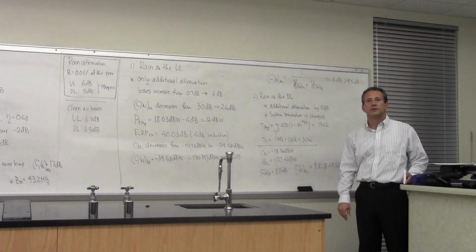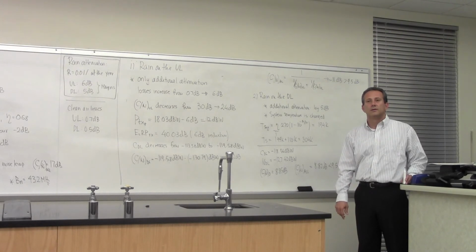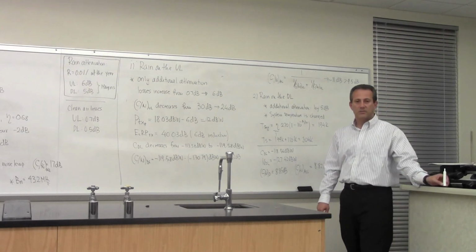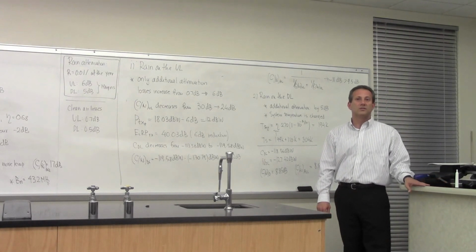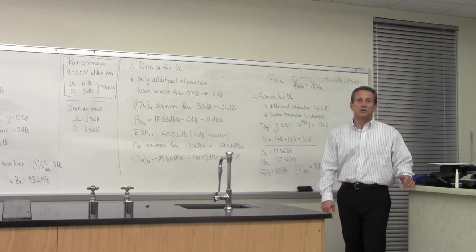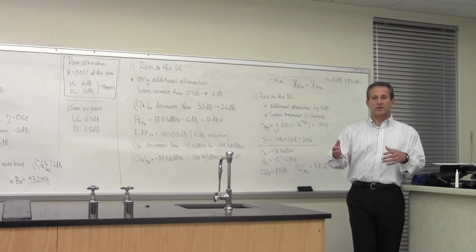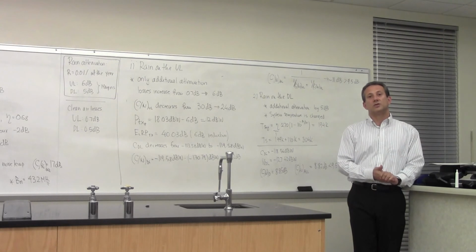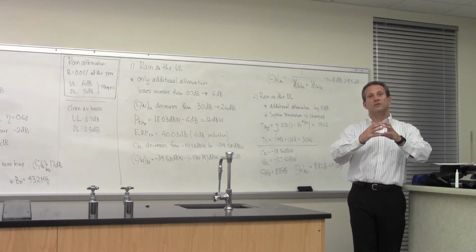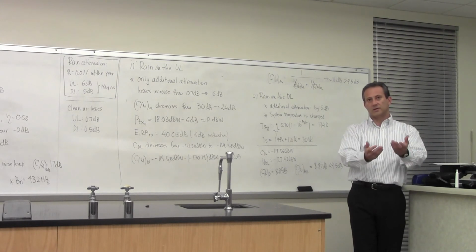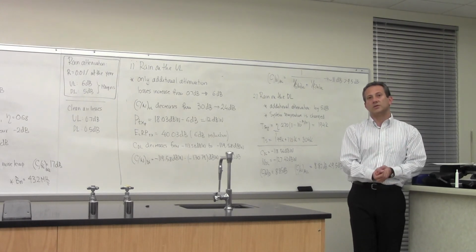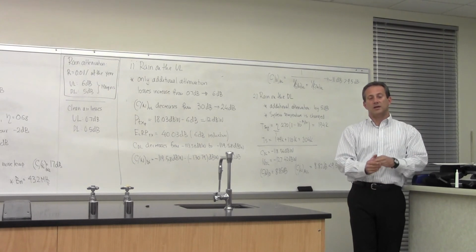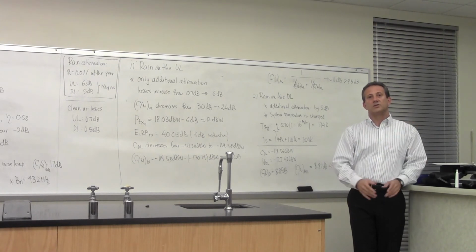Just a quick question. Why do we worry about system noise temperature on the downlink side, but not the uplink? On the uplink, the system noise temperature stays very much constant, right? Because regardless of whether it's raining or not, the earth temperature does not change much. Earth is in the main beam of the antenna, and whatever the temperature of the earth is, that is what is experienced by the antenna. In that case, the background does not change.